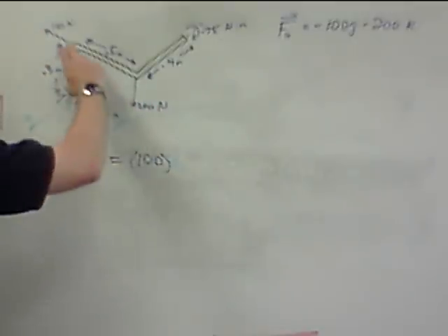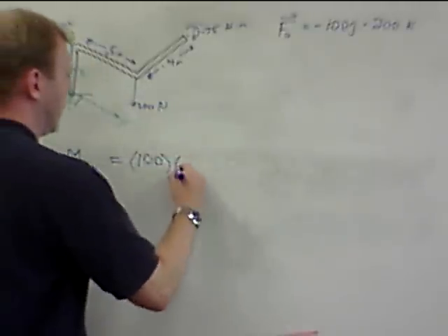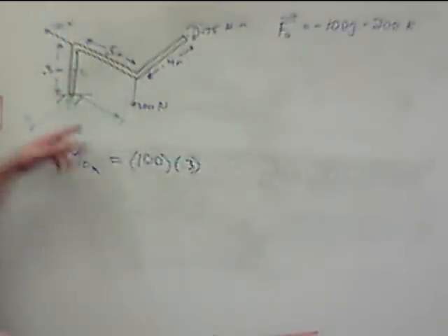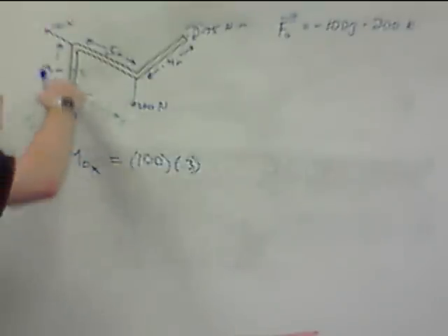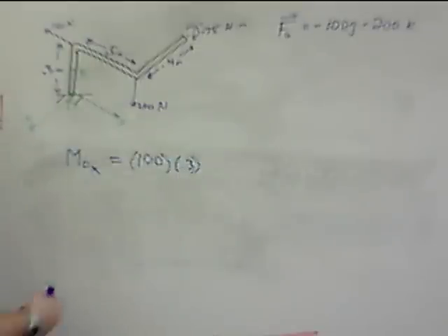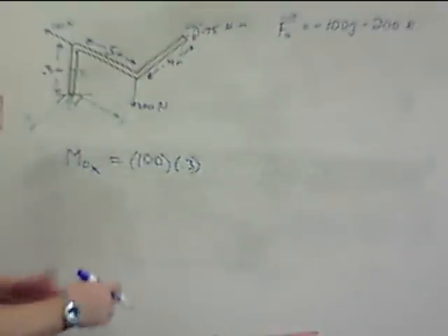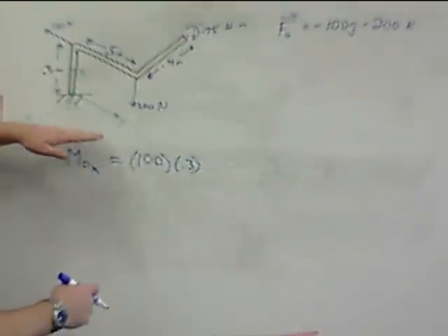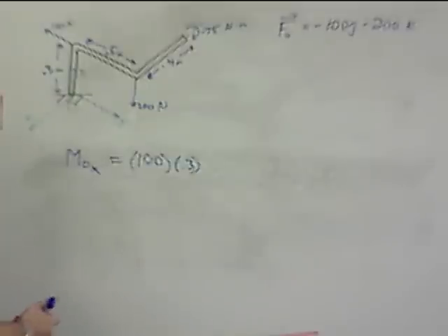The distance between them is this z-axis distance here, that's 0.3. So we get a force acting in one direction horizontally around this other axis that's also horizontal. It's the perpendicular distance that's important here. It's confusing because these are both horizontal, but because it's three-dimensional, they can both be horizontal and be perpendicular to each other. So that gives us the moment due to that force.